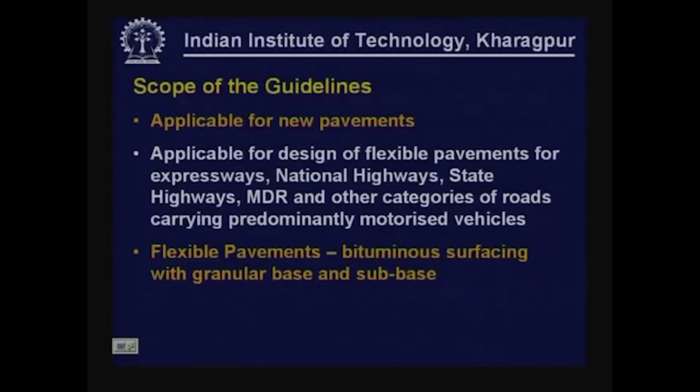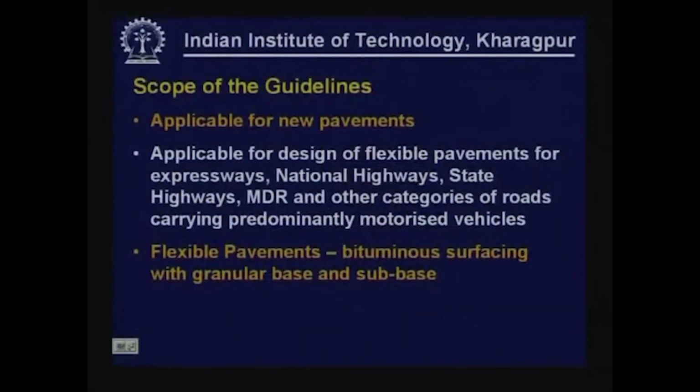Also, these guidelines are applicable for design of flexible pavements for relatively high volume roads such as expressways, national highways, state highways, MDR, ODR and other categories of road having relatively high volume. What we are trying to indicate here is that these guidelines are not meant for designing low volume roads such as village roads. Also, these are obviously meant for flexible pavements, typically having bituminous surfacing with granular base and granular subbase.